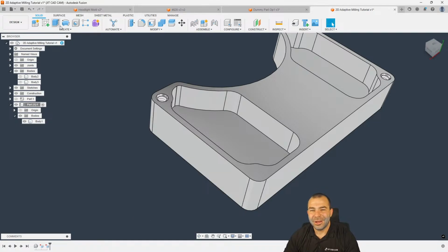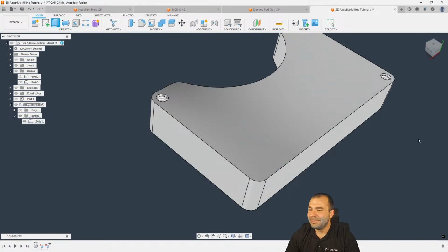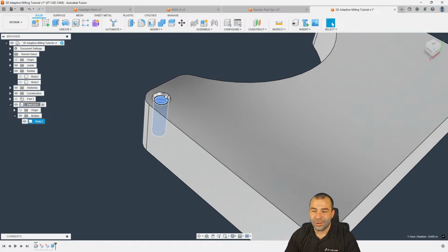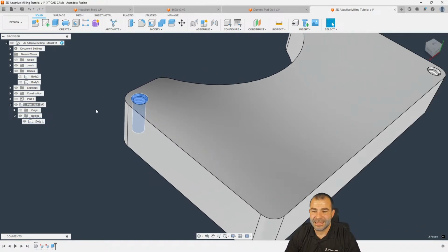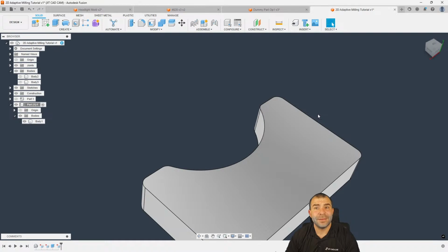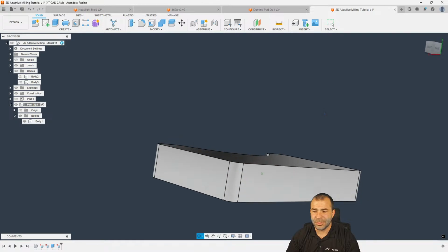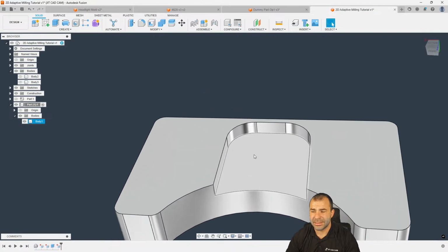But on this part, we could actually do an extrude because these are square pockets. Pockets are gone. This same method that we're doing for a casting, if you guys are dealing with flame cut parts or water jet parts, the idea would still be the same. Commonly, most of you that have ever worked with the EDM even, you add some extra material here for the EDM to come through. I'm just manipulating said body.